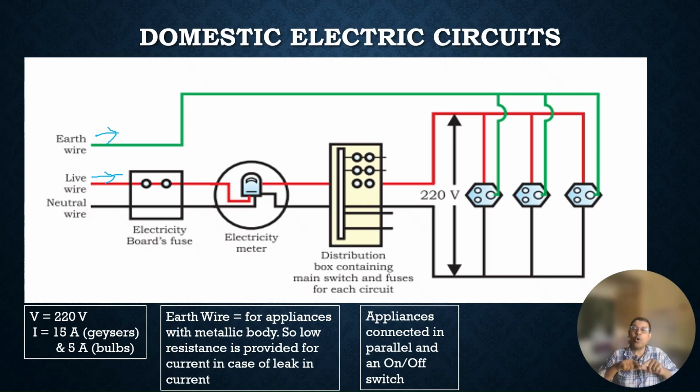This wire will connect all our appliances. If the appliance supports connection to the green wire, then it will be connected to our appliance, and then that green wire will also be taken to the earth, the actual earth. It will be connected to a metal plate, and then that metal plate will be connected to the earth. I will show it in another shot. It is there in my building as well. And then the neutral wire. The neutral wire is a black wire, which helps to complete the entire circuit when the switch is on in different rooms. So what is the typical voltage in a home?